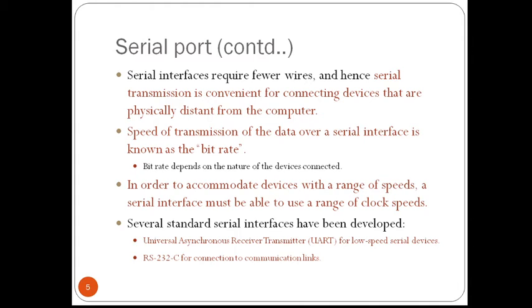That's why, with the double buffer, the transfer of the second character can begin as soon as the first character is loaded from the shift register into the data in register. That is why a double buffer is used.